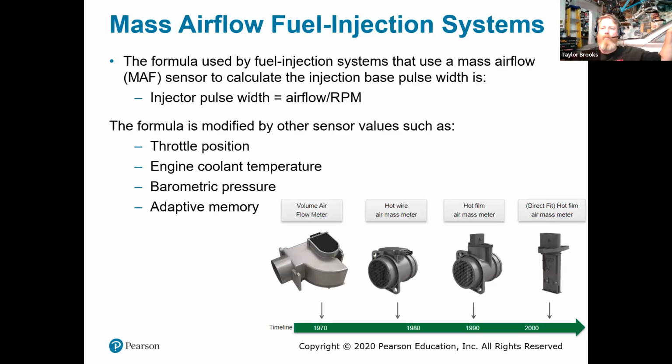One of the unique things with 944 naturally aspirated cars, they have a metal intake manifold. It's cast aluminum, and it's got these really long trumpeted runners for really good high RPM operation, while also allowing for a little bit of low end torque with how they were angled. But we start to bring it up on RPM, and we're going up, we're going up, and you can hear dink, dink, dink, dink, dink, boom. What had happened was one of the bolts came loose because we hadn't used Loctite, and we could hear it ricochet down the intake manifold, get past the intake valve, and go into cylinder number 4.